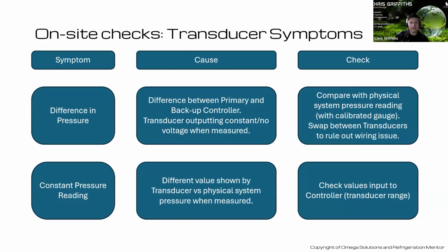Yeah. One of the issues I've found in the past is that work's been done on an island, and the transducer's been left valved shut. Afterwards, all those controllers are linked to this, but that pressure is not changing because it's trapped in that short section of pipework, and results in incorrect control and liquid flowing straight back to the compressors. And thankfully, not quite a large enough island to really damage the system, but it needed investigation. And that's the issue. So again, it goes back to commissioning checks. Make sure that transducer is actually reading what it should be.